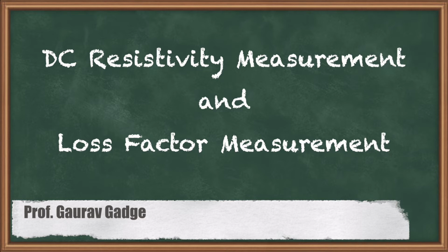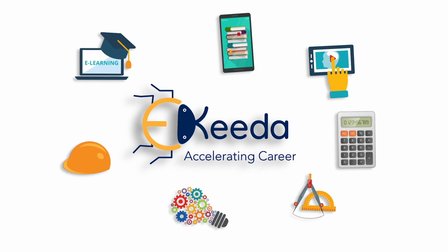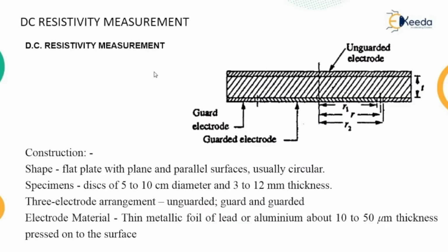We are going to discuss our next topic, that is DC resistivity measurement. So let us begin with the discussion. Here we have a resistivity, as I already said in the previous lecture, given by the equation R is equal to rho L upon A. For this DC circuit, rho, the resistivity, is given by the resistance of the insulating material multiplied by the cross-sectional area of the material divided by the length of the material. That is the expression for the resistivity.